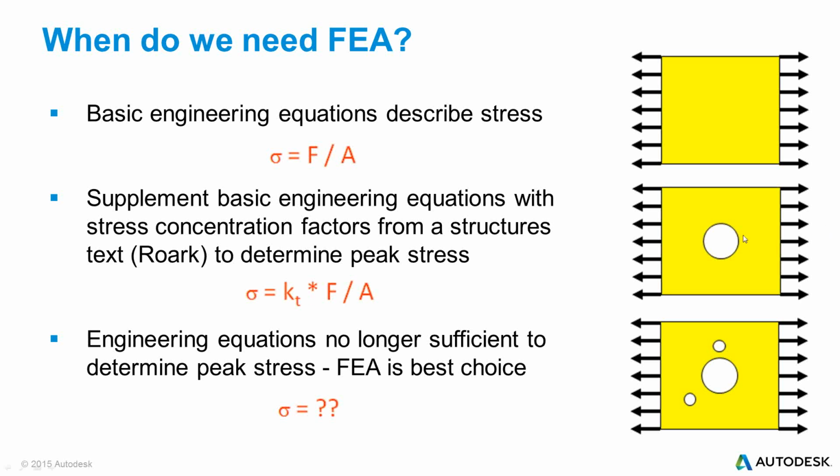I can use it, but I don't need it. Once I start putting more holes in here, I can do my KT equation and come up with some rough ideas, but if I want to know the actual stress in the tendons and how the load is transferred around through these and where the high stresses are, I can get some ballparks using hand calcs, but it's complicated enough that finite element is the best choice to do something like that.